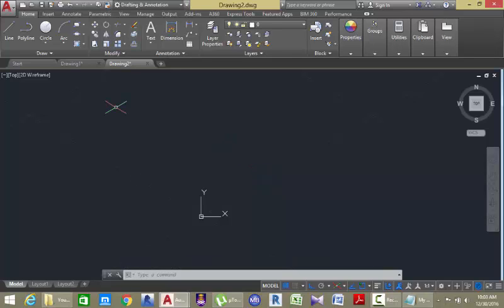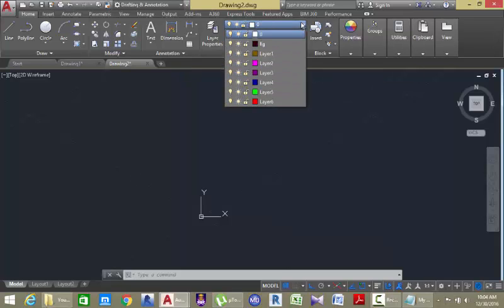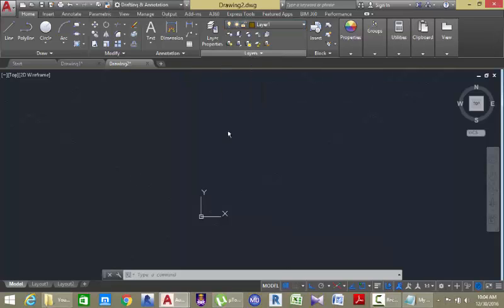We're going to draw a table 60 by 30 by 30 units. So normally when I draw in isometric mode, sometimes I prefer to draw everything in the top plane, then I can move them afterwards and also use them as a reference when I need them. So go to the home tab, layer panel, and click the down arrow. Select the layer 1 option.